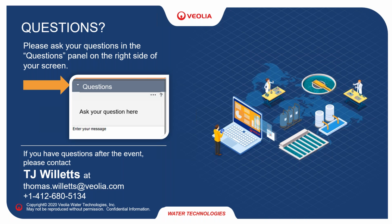No, the temperature is fixed. So the PCF and the ACF work at the lowest temperature possible and the lowest vacuum, around, let me say, 85, 90 Fahrenheit degrees. So we keep the temperature stable in order to evaporate at the lowest temperature and at the maximum flow rate of the water.